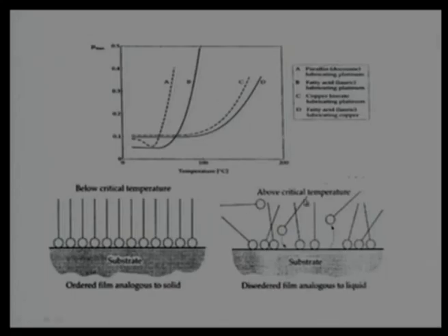That is the reason why we do not get very good performance at high temperature, or temperature above the critical temperature. In that situation, we need to think about whether the lubricating oil satisfies our requirement. If we know the operating temperature is high, then we need to choose a proper lubricant additive. Whatever lubricant additive you choose, it is not necessarily going to survive and work. It works only below some critical temperature, and does not work beyond that.